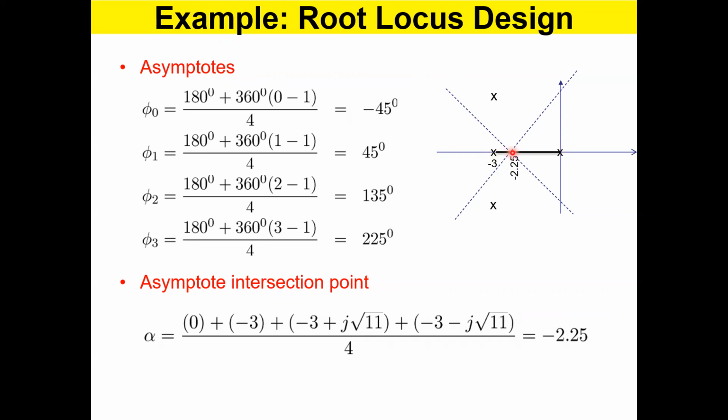these two poles meet up at some point, minus 1.23. That is the point where these two poles meet each other, and after that, it will split. One goes up, the other one goes down. So now we can safely say the one which is going upwards will align with this asymptote. The one which is going below will use this asymptote to reach infinity. So it is logical to imagine it that way.